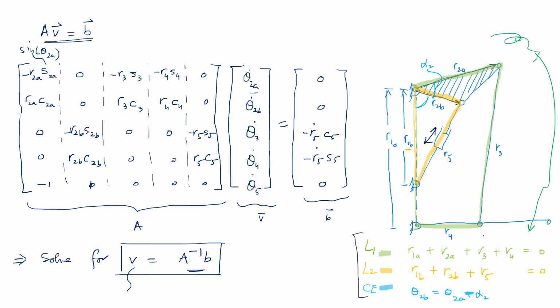So once you're going to solve these, you're going to get all these unknowns, and that is going to give you the realization of how the joint velocities are taking shape when you provide input in terms of hydraulic actuators driven by the hydraulic pump. So this is it for this particular problem. We have solved it.